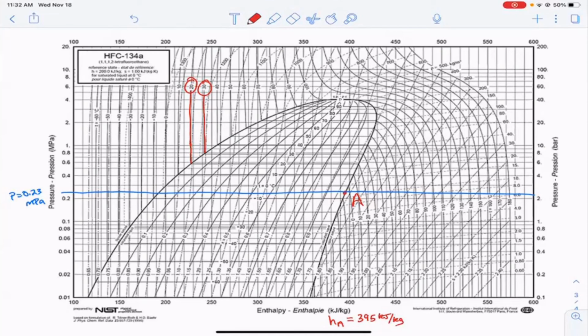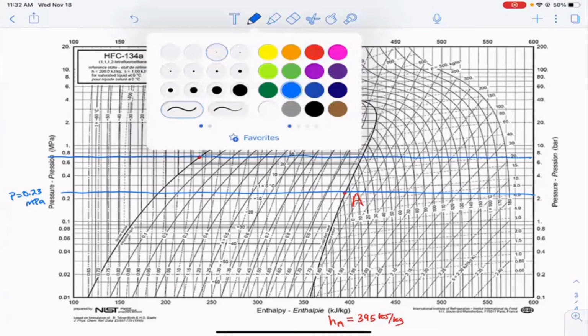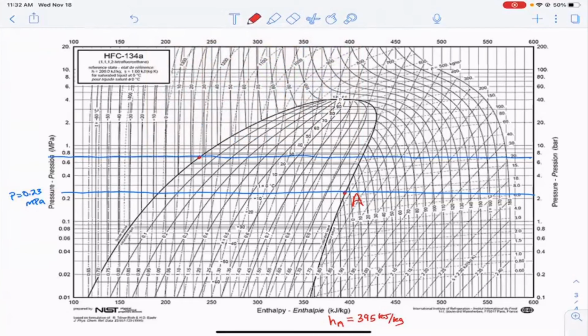I'll just find the middle and go just a little bit positive of the middle, to get to 26, and then I'll do the same thing I just did a second ago, and I'll draw the line horizontally on the diagram. And so now I have state A and C immediately in the problem. And then if I want state D, I just go straight down from C. So that's D, because that's still a valve.